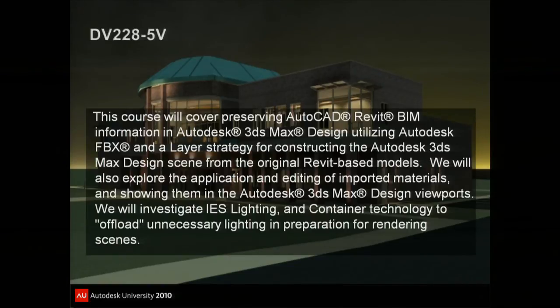I'm also using IES lighting. The whole reason I went with an FBX workflow versus using the AutoCAD workflow is, I mean, they're both great workflows, but I'm not a lighting engineer. So when it comes to lighting, I really want to preserve what's coming out of the Revit-based models, because that's what the lighting engineers are telling me the lighting needs to be. So that's why we're using the FBX workflow for this.